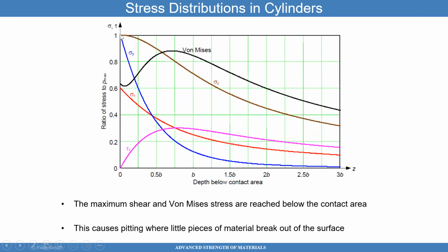So again, one more time, if you have a ductile material, it's likely going to fail following more of a von Mises situation. While if you have a brittle material, it's likely going to fail, initiating at the surface, and max principal stress is a better measure of that. Any questions so far about that?